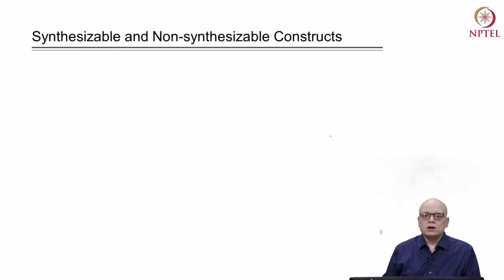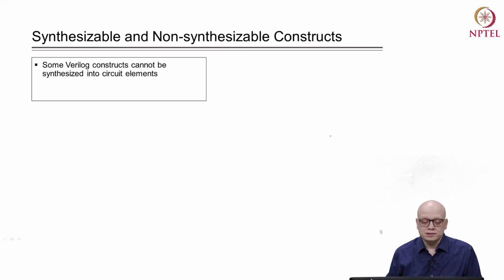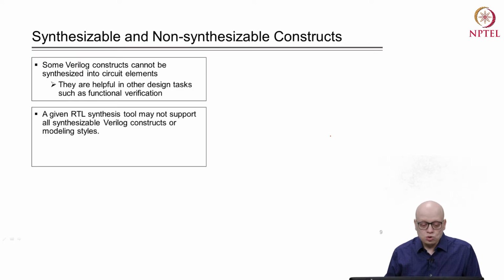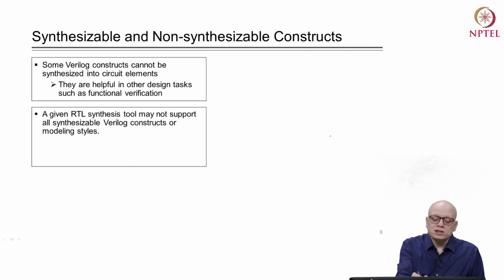Before going through various RTL constructs and understanding how they are synthesized to logic gates, first let us understand which RTL constructs, or Verilog constructs, are synthesizable and which are not. Why? Because some Verilog constructs support other design tasks such as functional verification, and those are not meant to be synthesized. So, a given RTL synthesis tool may not support all synthesizable Verilog constructs.